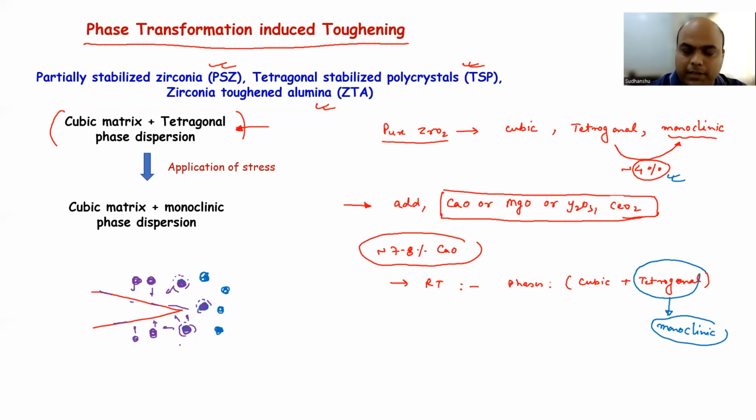That is point number one. Second, if the compressive stresses are large enough, you can see cracking, micro cracking. So ZTA, zirconia toughened alumina, can show both. It can show phase transformation induced toughening, and it can also show micro crack toughening. Okay, so you can have the compressive stresses as we have discussed just now for partially stabilized zirconia.